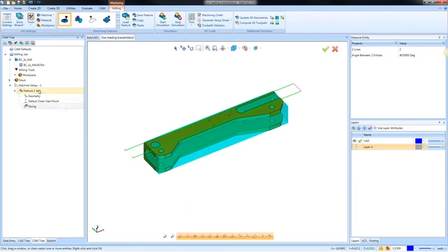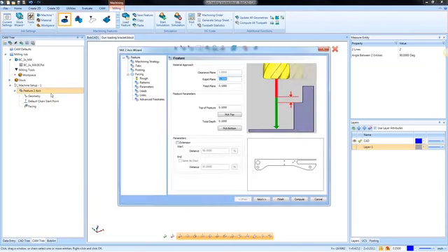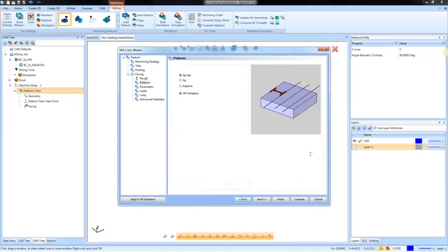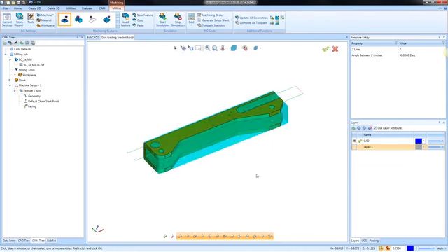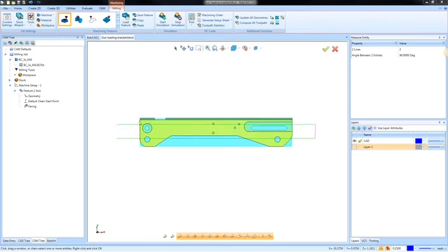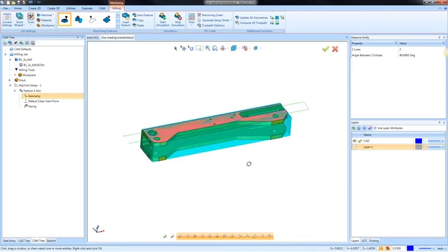So what I'm going to do is I'm going to adjust that first pass. Again, I'll edit this feature. I'm going to go to patterns here. And then this has a first cut offset. This allows you to move that first pass over a little bit by any value that you put. We can recompute. And then what that will do is offset that geometry so that it doesn't start 50%. Okay, so you can see even selecting this irregular shape here, I'm able to come in here and to face this part down, no problem.